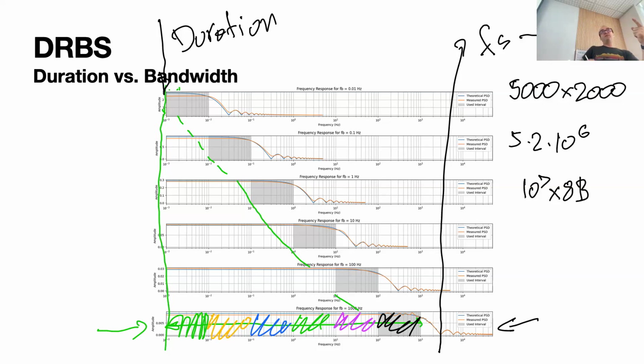And we are measuring maybe voltage and current, so this is times 2 at least. But if we have a stack of, let's say, 10 cells, we measure each cell separately plus the current, so this will become times 11. And if we start to multiply this, we suddenly reach tens of gigabytes of data. If you have this amount of storage, and if you can afford it, use just one excitation signal, generate 10 gigabytes of data and do whatever you want with it.